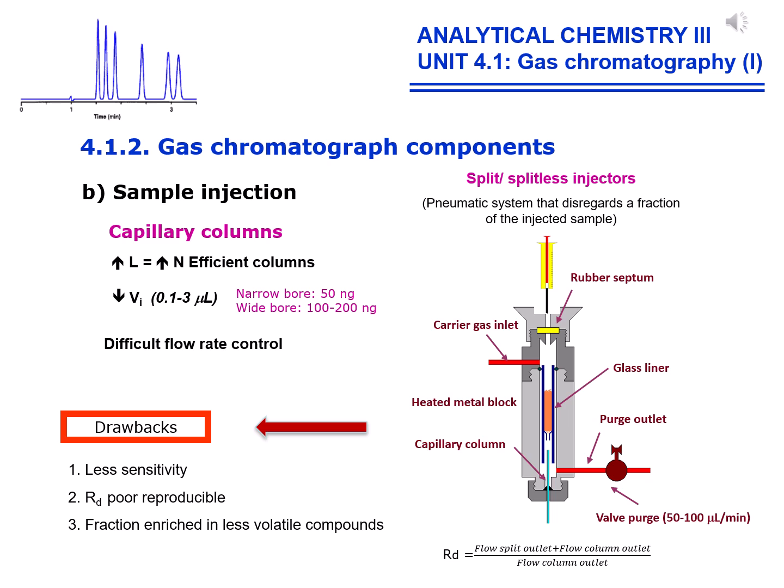The carrier gas reaches the vaporization chamber, where it's mixed with the injected sample as shown in the figure. A variable vent valve, usually set between 50 and 100 microliters per minute, divides this flow into two unequal fractions. The larger flows out of the injection chamber, dragging most of the introduced sample.